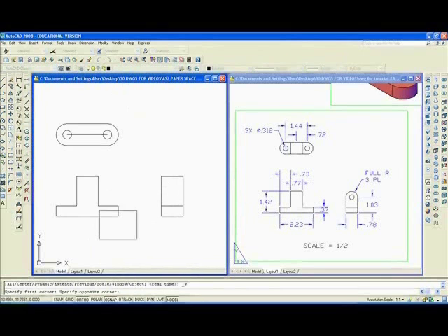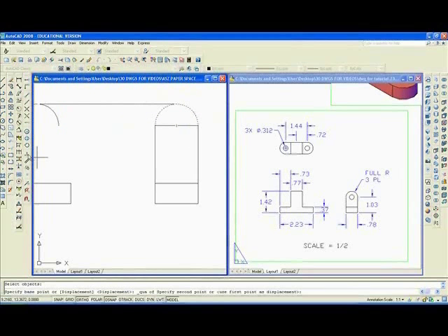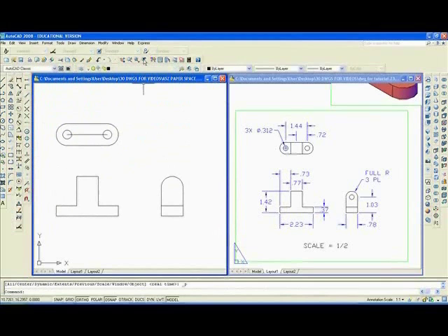And we'll zoom in on this right side view. I know that I can fillet 2 parallel lines and make a full semicircle, but that's too high now, so I have to move it. M enter. I'm going to move that from its quadrant here to a point that is perpendicular to this line here. Now you're free to erase this line, and you can trim from the curve these two extensions and zoom previously.